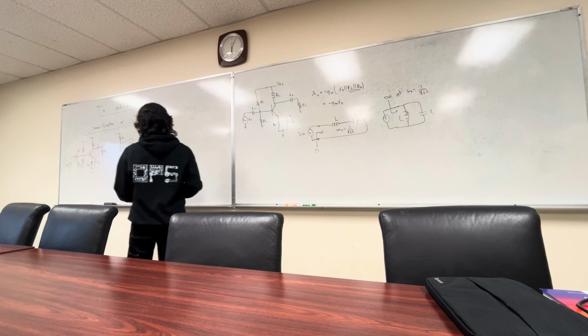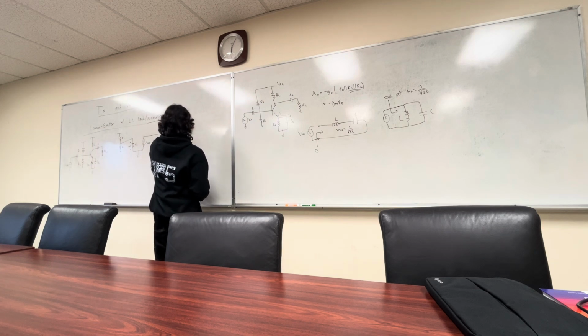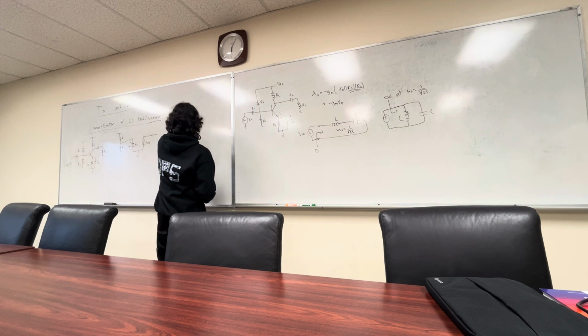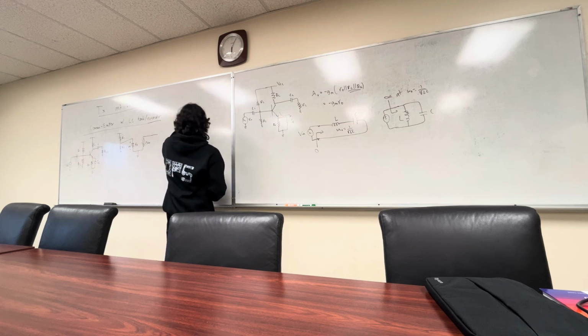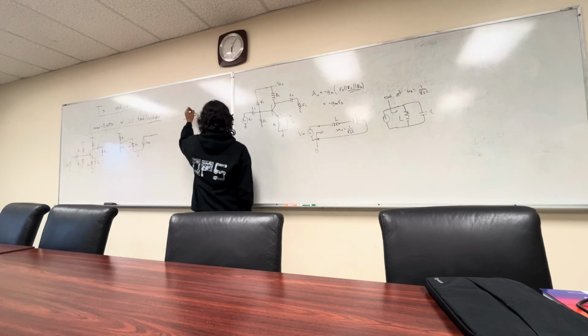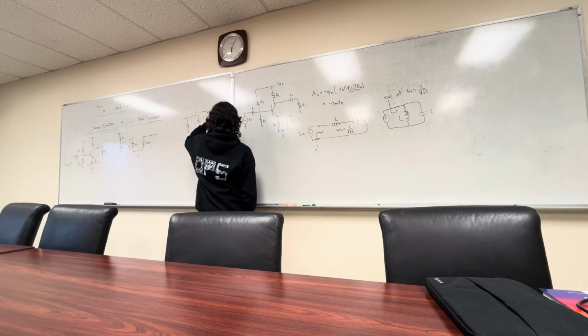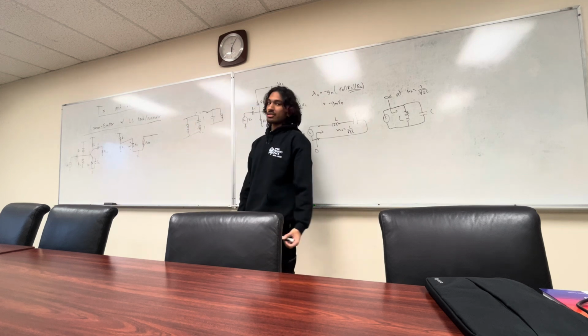And although I just erased it, if we look up into the collector, it looks like we have an inductor, and in parallel we put a capacitor, some resistance. We want to ideally transform this into something that looks like this. That way, the inductor can sit right there, and we just have a parallel RLC tank.